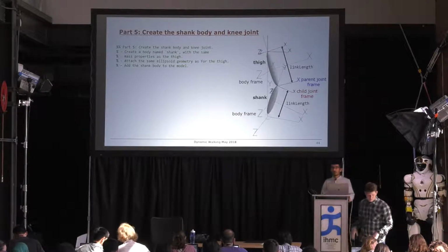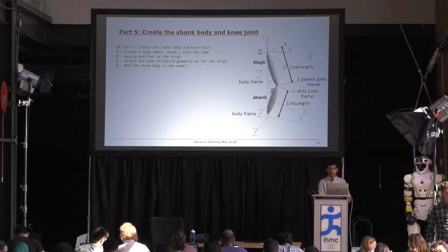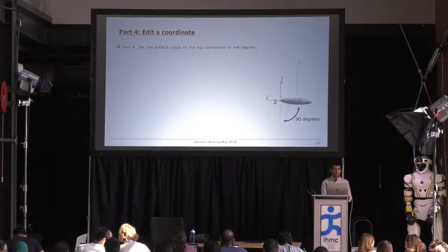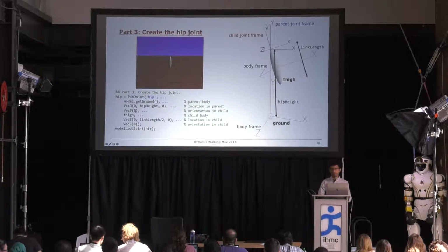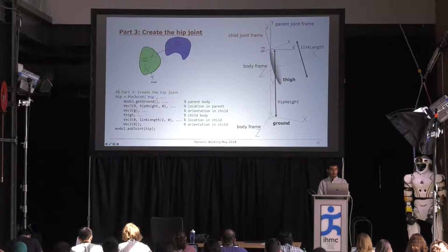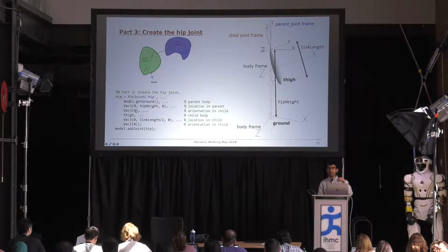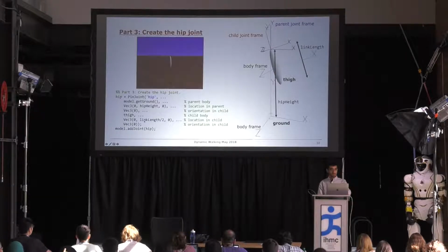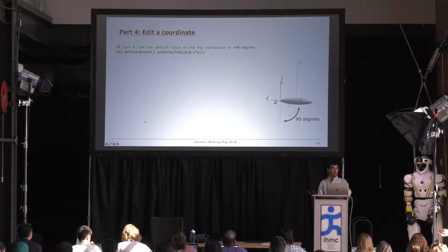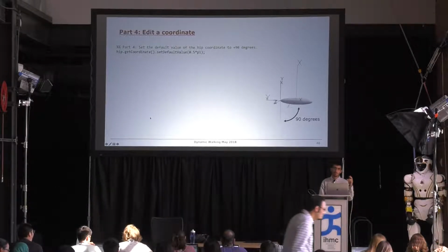Nick said some people were wondering about Vec3, where we pass in only one argument. This ends up creating a Vec3 where each element is 0. And also for inertia, we saw you did inertia of 1. That creates an inertia tensor where the diagonal elements, the principal axes, are all 1 in SI units. Right, and you have to use OpenSim Vec3s or vectors in those cases. You cannot yet use just MATLAB arrays.